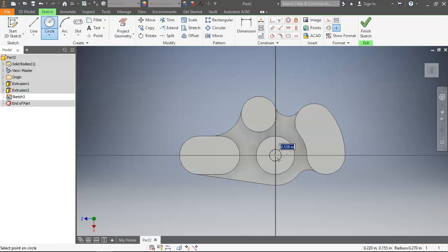We see 1.123 and 1.125 ream. And what this is talking about, guys, is what's called tolerances. Tolerances tell the machine shop or the manufacturer the range of dimensions that this dimension could be. So that's saying that this hole can be as low as 1.123 and as high as 1.125. So for dimensioning it in Inventor, you can do any of those numbers. I'm going to do the 1.125 just because it's a nice whole number, 1.125.